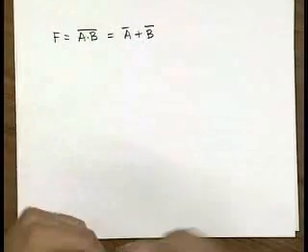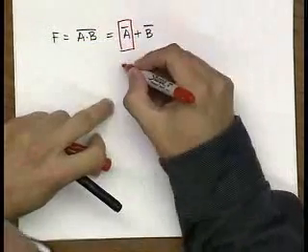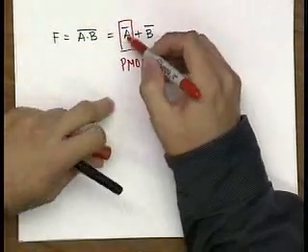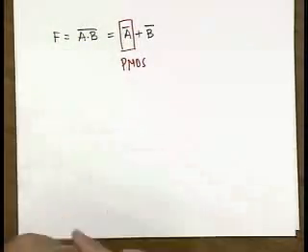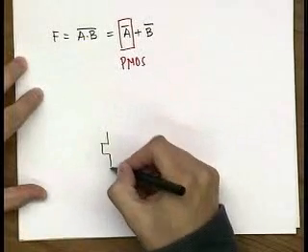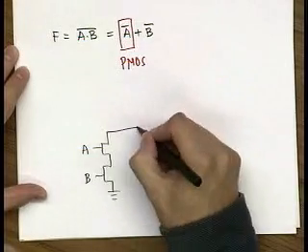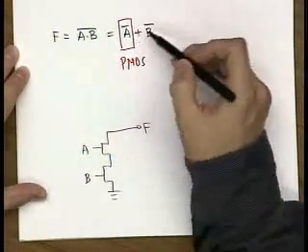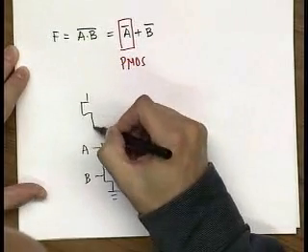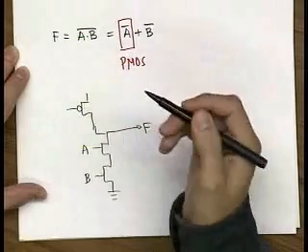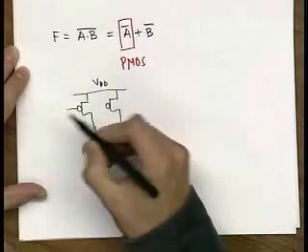Whenever you have a situation like this, this means this is your PMOS, because PMOS is driven by the complementary signal. So what this tells you is that a NAND gate, using this principle, is constructed simply by using a serial connection of two transistors A and B to ground. This is the function. And now I have a parallel combination of PMOS transistors, driven with these complementary signals using this De Morgan principle. And that's how you construct your NAND gate.